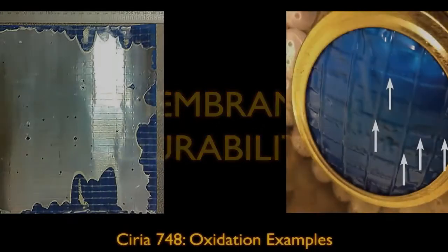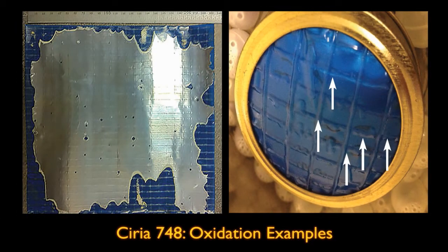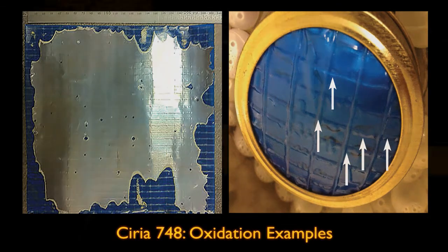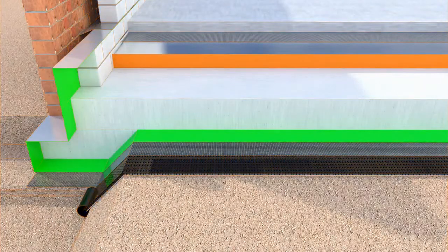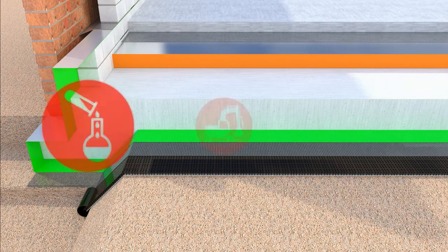Next, we look at durability. The actual VOC resistance is only one facet of membrane performance that must be considered. Membranes must also be able to resist degradation processes such as oxidation, particularly if they are based around foils. As part of an appropriate overall design, a membrane of low resistance to a liquid contaminant may still be suitable provided exposure to that liquid form is minimised.